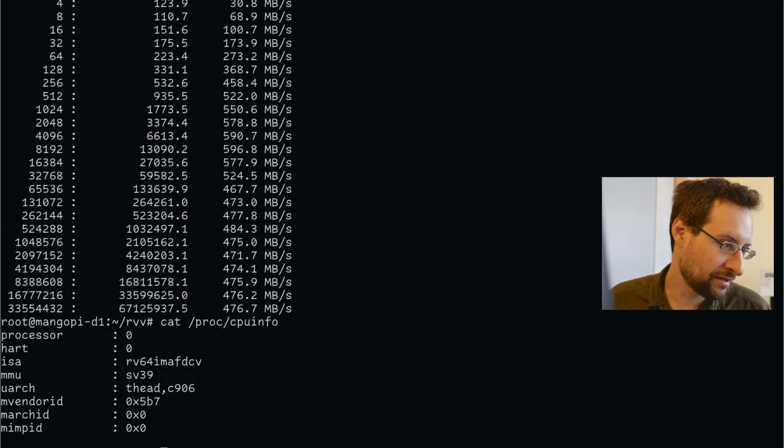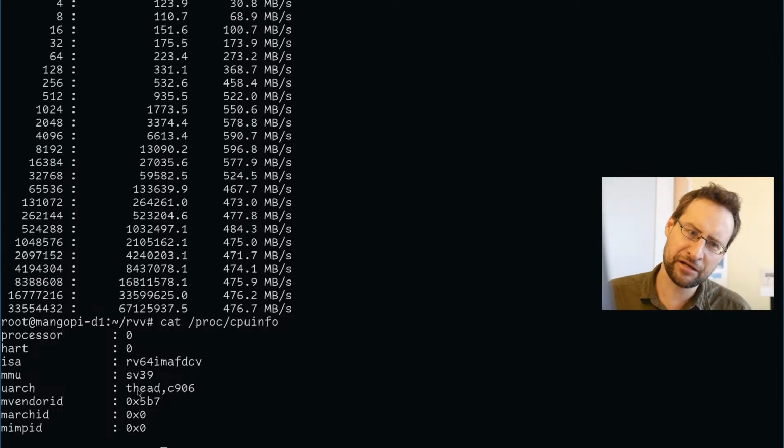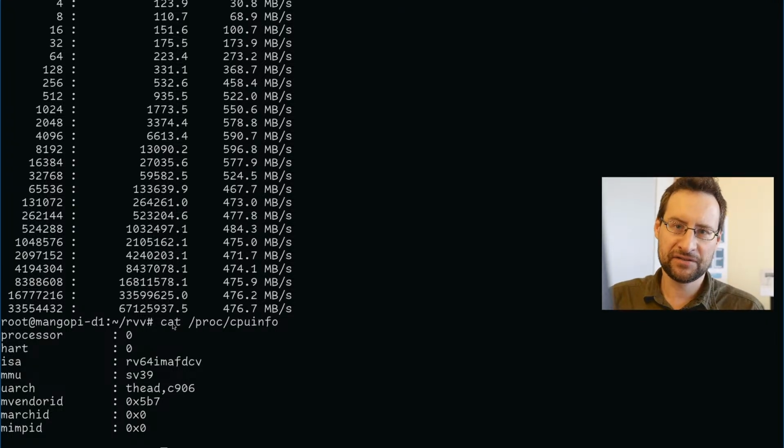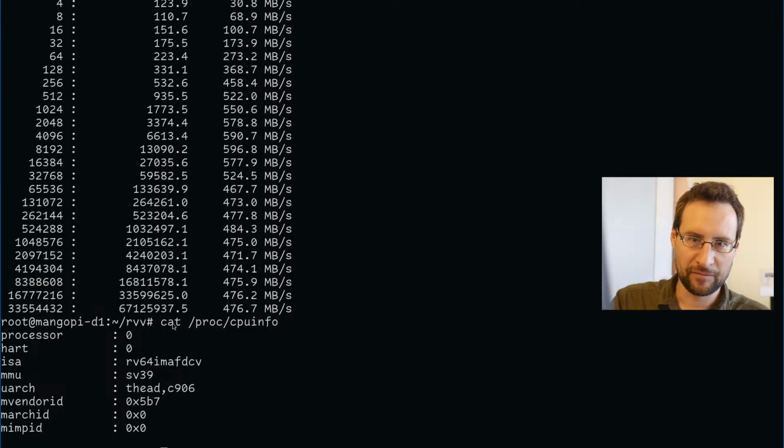Alibaba's subsidiary, T-Head Semiconductor, implemented their T-Head C906 core with a draft extension for what SIMD, single instruction multiple data vector extensions, are. Videos are on my more main channel. If I repeat everything each time, the videos double and triple in length. Basically, more performance for processing more data with one instruction, similar to MMX, 3DNow, SSE, AVX on the x86 side, or PowerPC AltiVec.